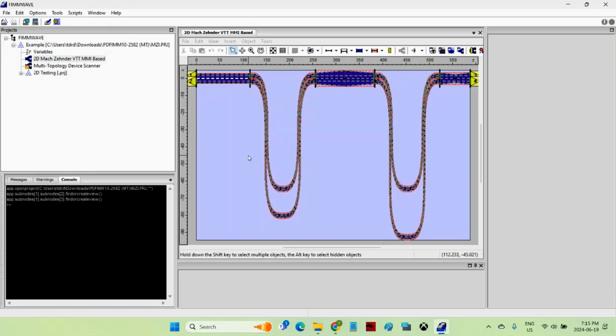First thing to notice in this example here is the scale. On the top here we're going up to 600 microns, and on the scale here down to about 100 microns. So a reasonably large simulation area. Certainly one that, if this was a 3D simulation, would take a lot of computer power for FDTD to solve, and until now would be impossible with EME, and in addition also impossible with beam propagation methods.